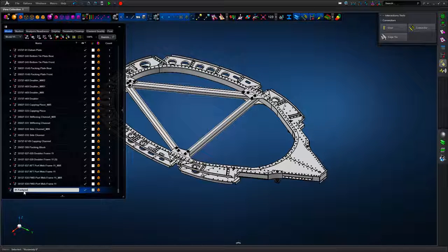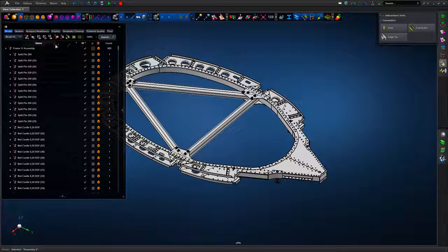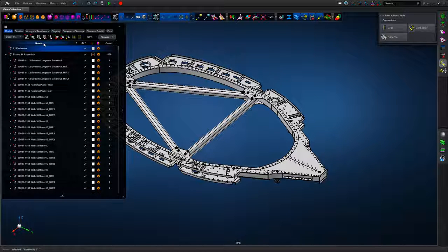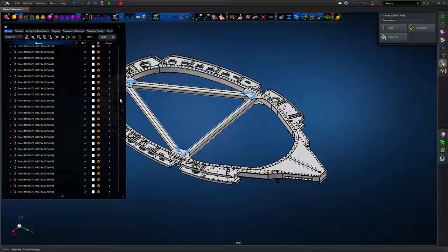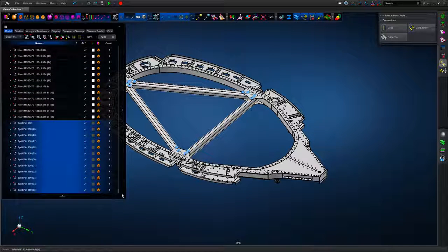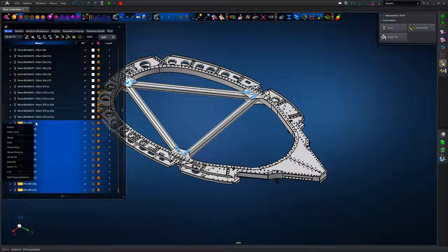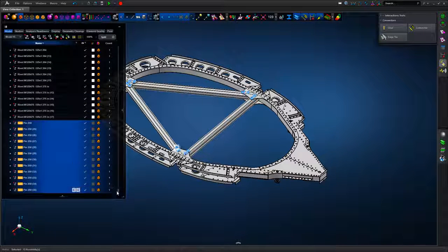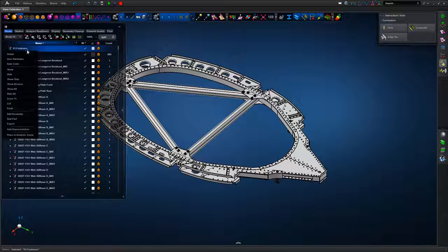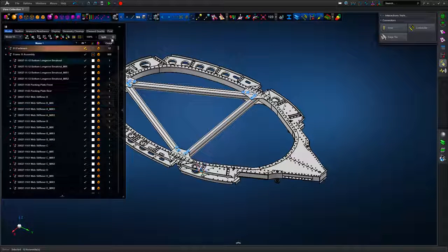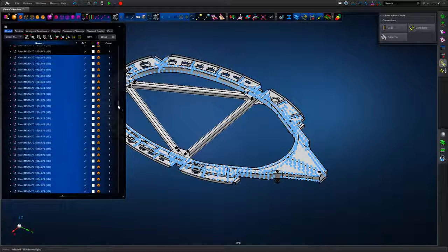We're calling it fasteners. So we're going to ultimately take out all of the redundant fastener definition for this first level model and just leave us with the structural entities. Based on the search string, we've got lots of split pins first of all. So using a split term within the search string, we can cut those entities out of the original assembly and then paste them into the fastener container subassembly to simplify the model.